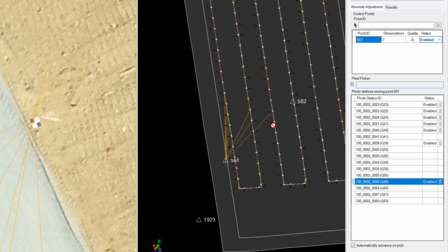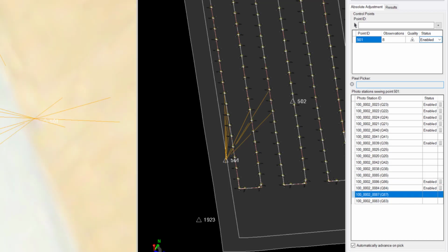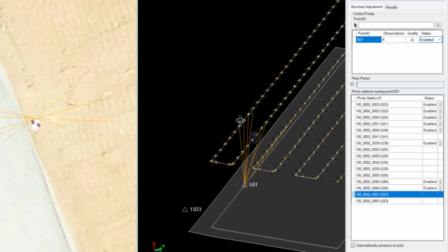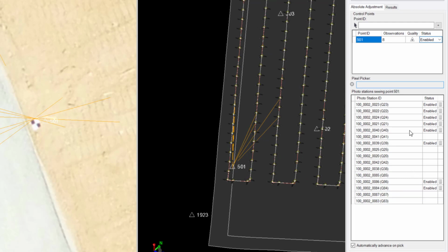And when we look here, then no surprise, this is now coming here from the 3rd strip. And then here I will make another measure from the 3rd strip. So really nicely connected here through the different strips. Of course, measuring all of them is not wrong. Ground control points are really our very important ingredient in this whole part.